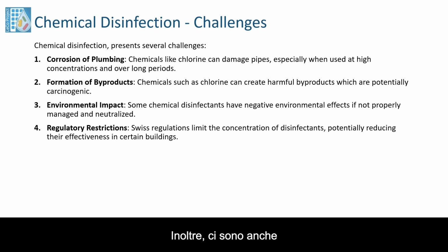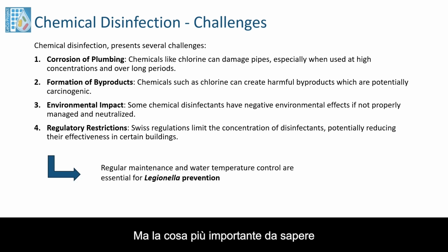Also, there is a negative environmental impact that should be taken into consideration, and the Swiss regulations limit the concentrations of the disinfectant, potentially reducing their effectiveness in certain buildings. And those regulations and restrictions should be looked at more closely. But mainly important is to know that regular maintenance and water temperature control are essential for Legionella prevention.